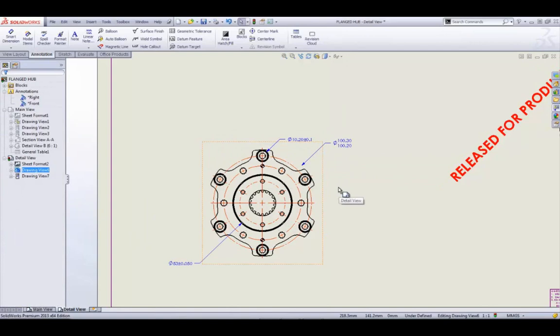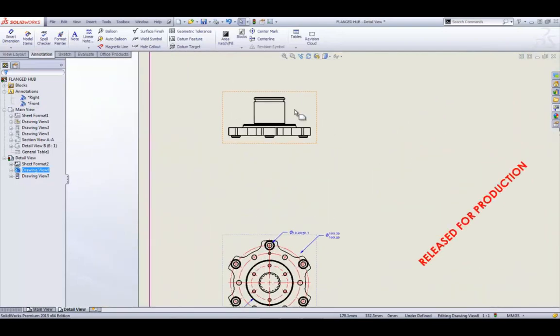So this is really neat if you're creating inspection drawings or something like that. When you're modeling your part up and you say, all right, this is what we're going to use for inspection, you put the tolerances in on your 3D model, and now you can actually sort through and just bring that in there. So I think that's handy.